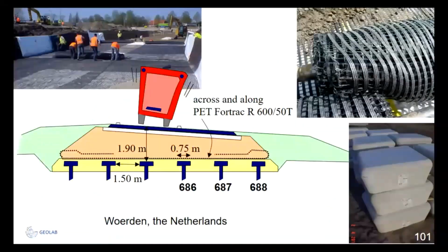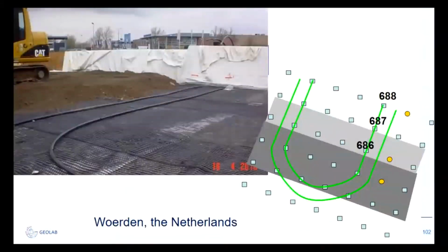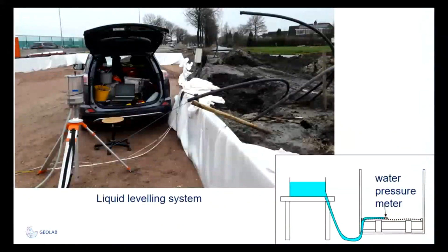And then we looked in the field. Here we have an exit of a highway, and we have those settlement tubes attached to the reinforcement. The subsoil support disappeared quickly. In this case, there was a thick peat layer and a sand layer on top of it below the reinforcement. This is the same, another project, also settlement tubes installed coming out at the side of the road.